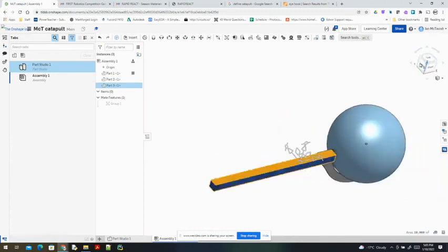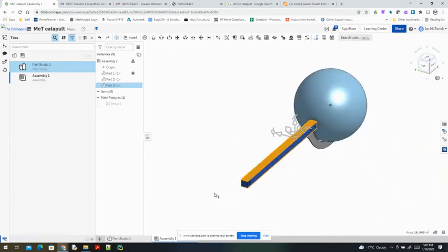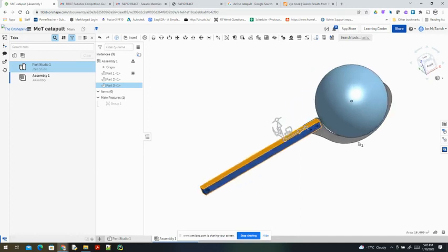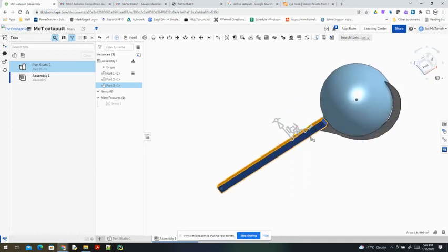the surgical tubing, and I would tie the surgical tubing to a point over here, and so that when it's up like this, it's tied tight. So pull it back, it's going to have a lot of force, and then release it. For a prototype, that's all I need. If I was going to do this in real life, like on a robot, then I would attach a string here or something that would allow it to winch back. And then that winch would have a locking mechanism so I can drive around. And when I'm ready to shoot, it releases the locking mechanism, and the surgical tubing shoots it forward.